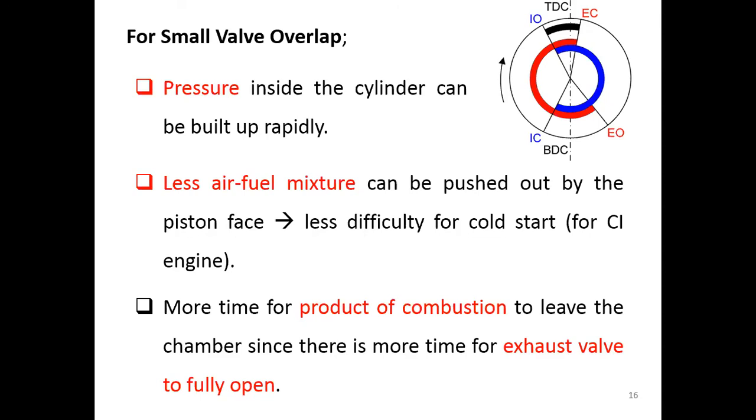Apart from this, you have more time for the products of combustion to leave the chamber. That means you have a small opening between these two, which means you have more time for the exhaust valve to fully open here. That means you have more of the products of combustion, the exhaust, going out.